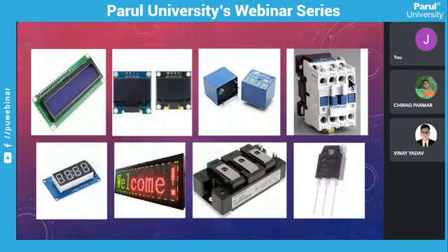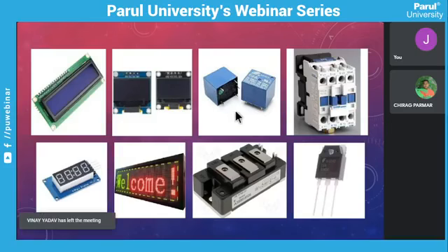The main difference is that the contactor connects all of the 3 phases simultaneously, whereas the relay just makes or breaks a single phase of a circuit. The relay is mainly placed between the live wire and the load, so it makes and breaks the live, whereas the contactor makes and breaks each and every phase of a three-phase circuit.